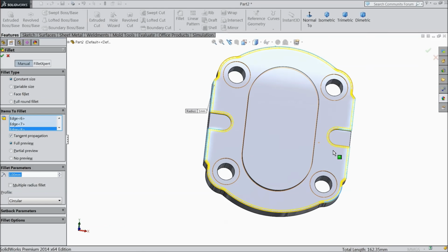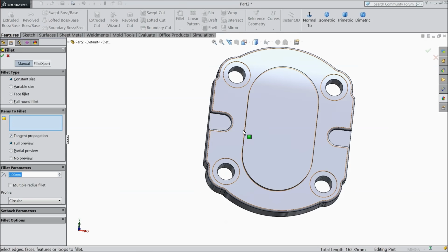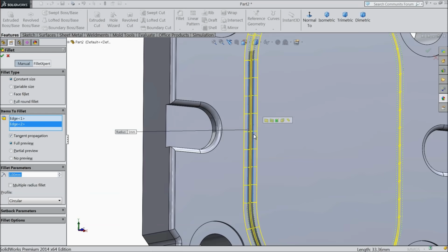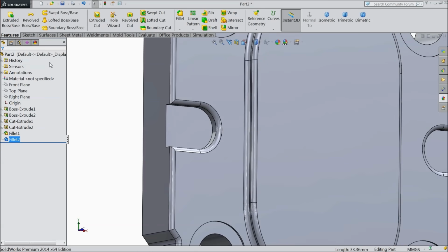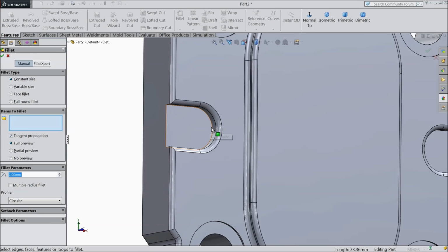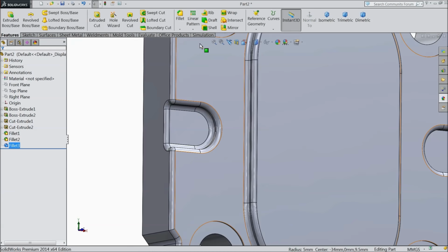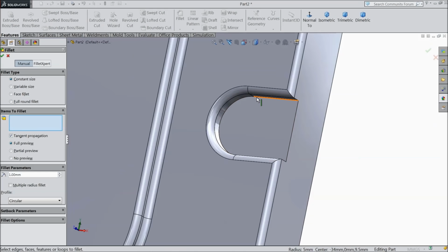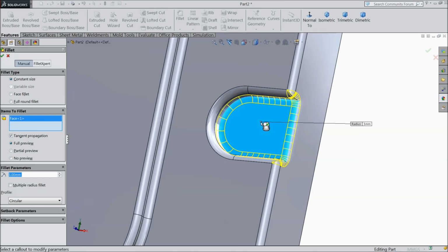So now upper edge selected. Okay, again choose fillet. Select this inside edge and upper edge, 1 mm. Again fillet, select this inside edge and this edge, 1 mm. Okay, and we will select one more time this side, or directly select this face.